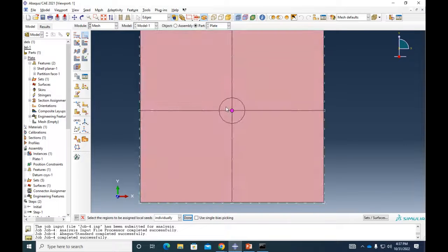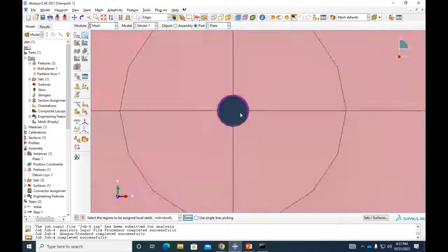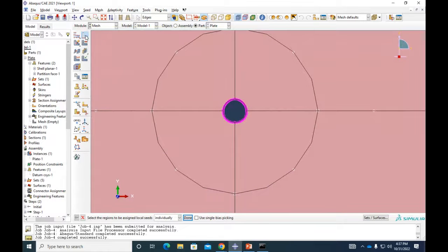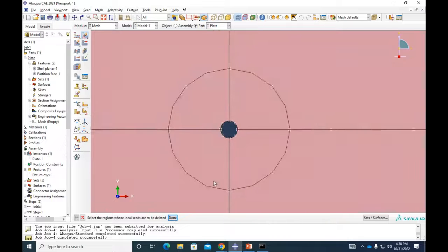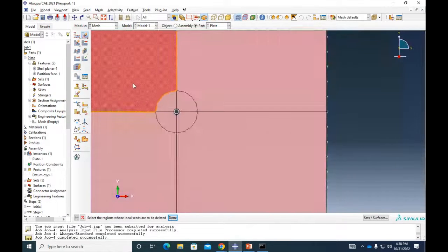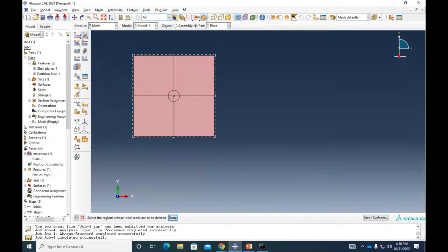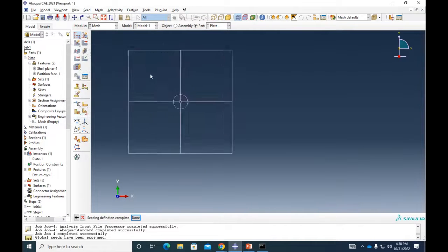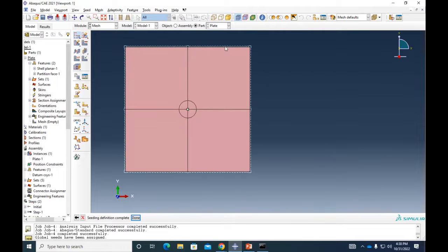So, these seeds that I had before, that we said that we had 200 elements in here, let's delete those, all right? So let's delete these seeds in here. Now, I'm gonna select an outer seed. So for everything, let's say that the seed is 2. So here, these outer edges are gonna be meshed with a seed of 2.